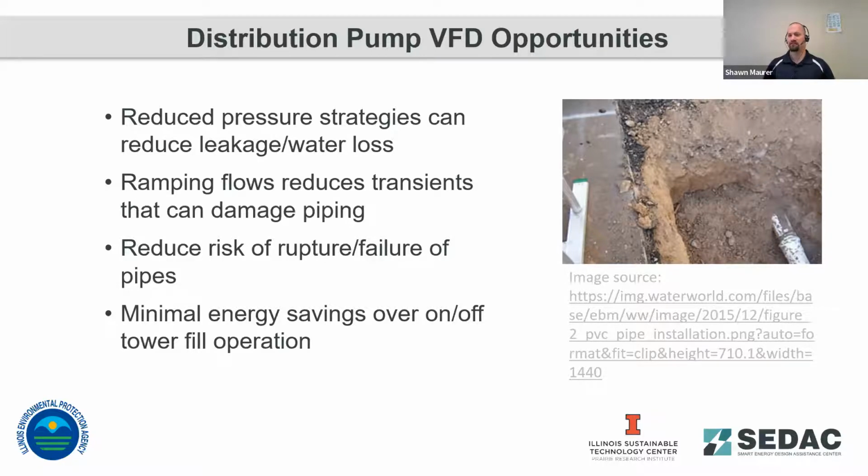This has a couple of different benefits. One, by reducing that required head pressure, you reduce the amount of energy that a pump needs to impart to the water to lift it up and fill a storage tower or to maintain pressure in your distribution network. But also, leaks in your distribution network are tied to that pressure. There's a minimum amount of pressure that must be maintained to make sure you don't have water leaking back into your potable water systems and causing contamination.